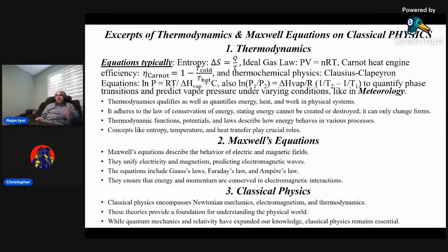So if we calculate that, we can prove that in order to get 100% efficiency, T cold, which is the sink, has to be absolute zero temperature, which is not possible in real systems. So the efficiency will be less than 100%, less than 1, which you multiply by 100 to convert to percentage.